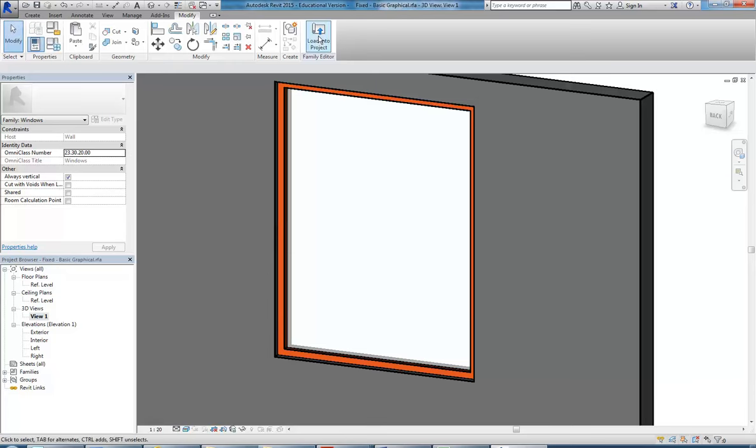So in my list now, I've got those two different sizes. Don't worry about the one that's got the name, that's just going to be the original size. And then back to edit type, and I might do one more size. So this one I forgot the millimetres, so I can just go to rename there and add those in. And then I'll duplicate and make another one, 8000.